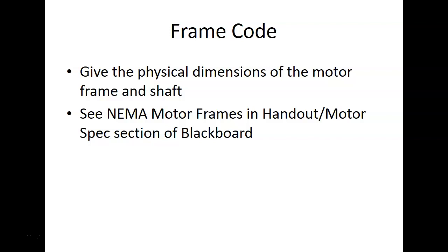So they decided to do this with frames. The frame specifies how far apart the feet are mounted, how long the shafts are, whether it's a double sided shaft with shafts on both sides, and the size of the frame. So what this means is that you don't have to buy the exact motor that's in your unit, right? Understand? All you need to do is buy a motor that matches or exceeds the motor you're trying to replace, because now all these motors are standard.